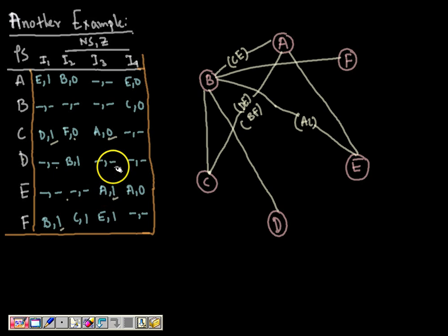Between D and E, there should be an arc because all the outputs are either not specified or same. And the next state transition is also to be considered as same. So DE is an arc, obviously. There should be an uninterrupted arc between DE.